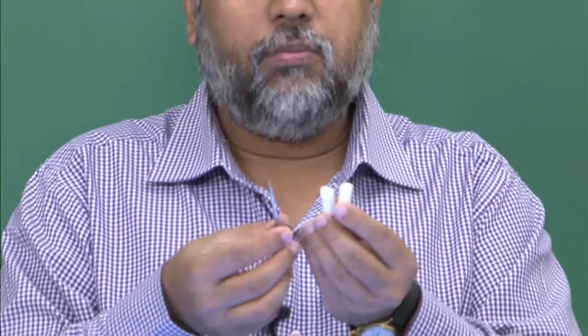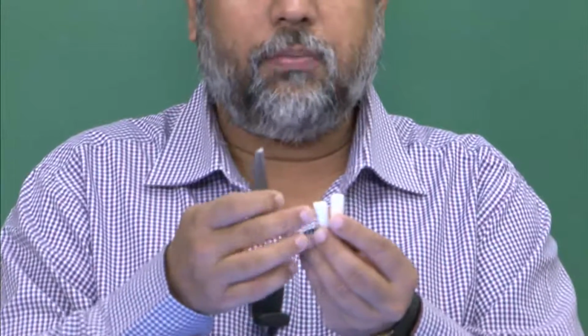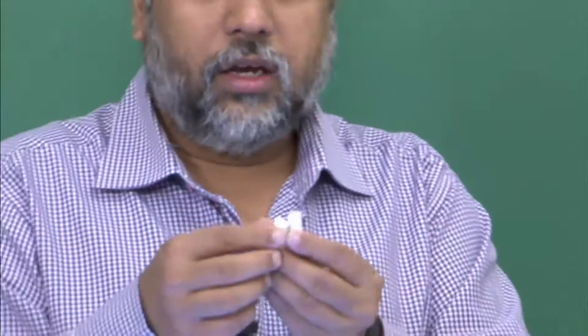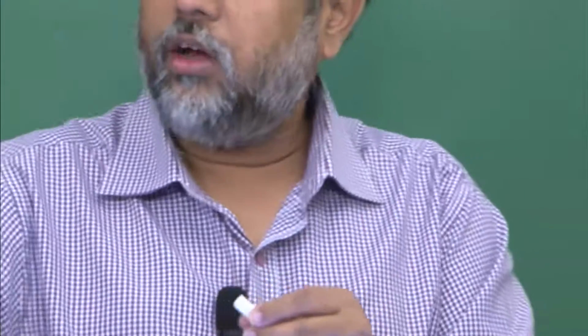So, you can consider these with respect to the ductile failures that happen in metallic samples. You can see that, much unlike the ductile failure, the brittle failure is much different. There is no necking, it just falls apart. Not only that, the stress at which it falls apart varies: if I take another chalk sample, you may actually get more resistance to failure. So, it varies from sample to sample. That is the point I wanted to stress.